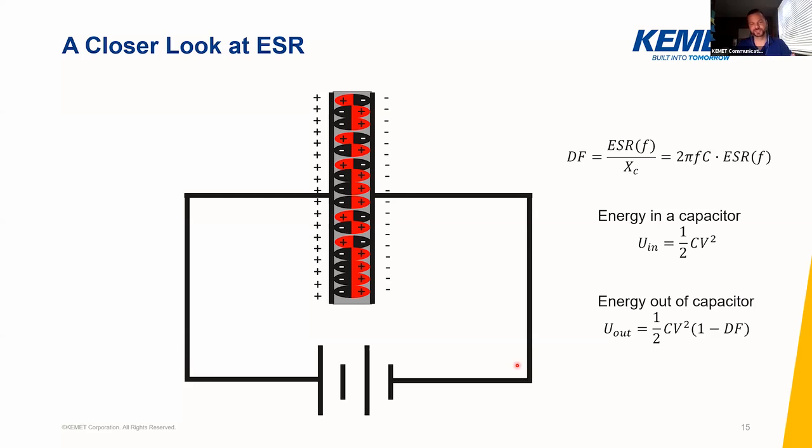let's say, locking some of those dipoles in place, and they have less of an ability to line themselves up with that electric field. So those dipoles that are now locked in place are no longer able to act as part of the capacitor. I'm going to make up a word here, but they're no longer able to capacitate, if you will. Think of it that way, because they're locked into place. So they no longer serve as an element that adds to the capacitance.